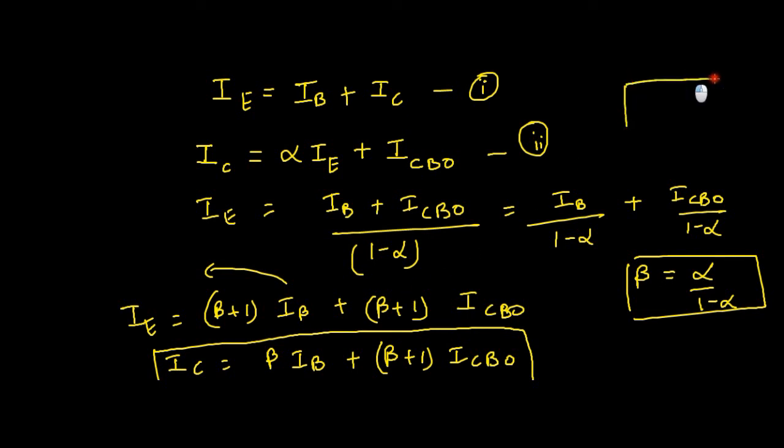Okay, so what happened? There are three terminals. There is a leakage current ICBO here. Once it reaches here, it gets amplified and moves towards the emitter. So this is nothing but (beta plus 1) into ICBO, just like this base current. This is the direction of actual current that I am drawing here. The electrons, however, move in this direction, which is another story altogether. The conventional current is always opposite to the flow of electron current. What I have explained is in terms of electron current.